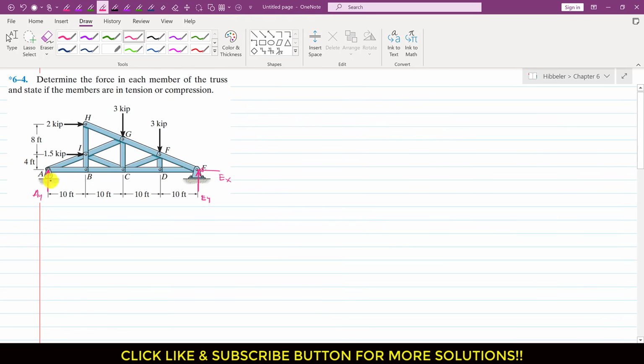To find these three support reactions, first I will apply the summation of moments about point E equals 0, and we will assume that the counterclockwise moment is positive. This 3 kip force and this 3 kip force are producing a counterclockwise moment about point E. So I will write plus 3, and the perpendicular distance of this force from point E is 10 feet, so I will multiply with 10. Similarly, this is also counterclockwise, so plus 3 into 10 plus 10, so this is 20.